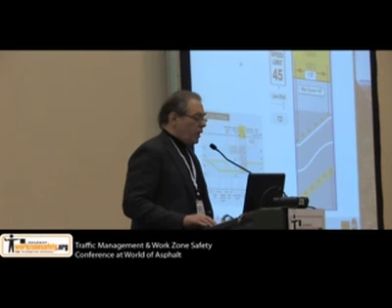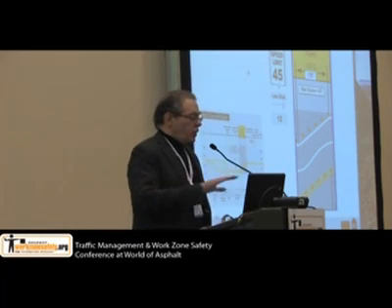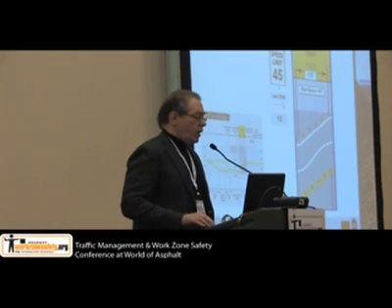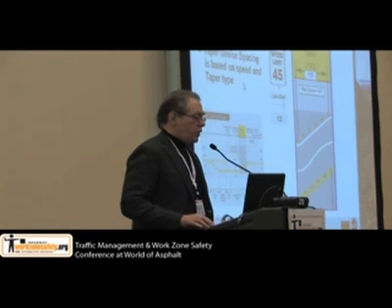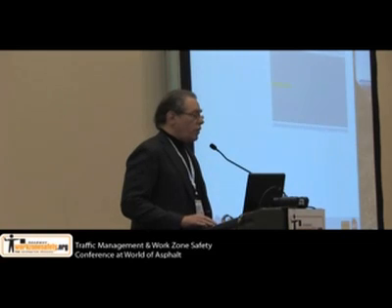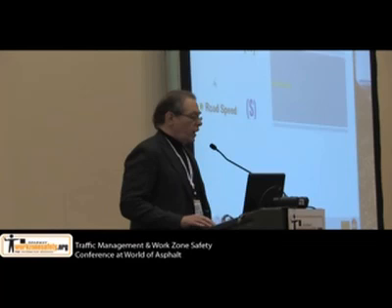And what is a shift taper? First off, shift tapers are normally 1/2 of L. L is based on road speed and lane offset. And the taper device spacing is based on the speed and taper type. Now, if we take this, just to show you, we have a little calculator out here, and L is determined by 2 factors, the lane offset and the road speed.